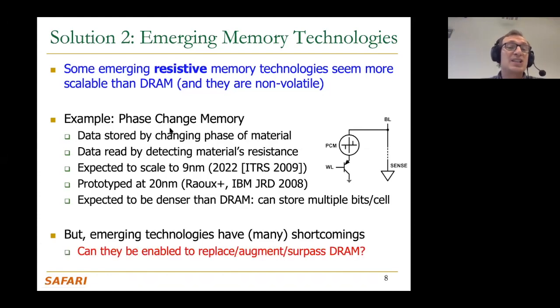For example, phase change memory has an endurance problem. If you keep writing to memory, at some point you cannot write to a cell because you've written too much, because contacts degrade because of very high temperature writes. As a result, you have a problem called wear out or endurance. You have limited endurance. So memory cells wear out. That's true for flash memory also. Flash memory wears out as well.